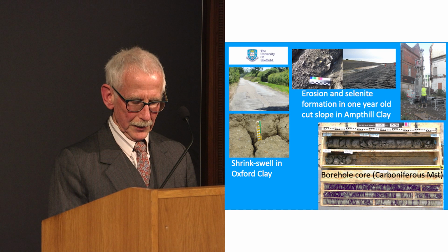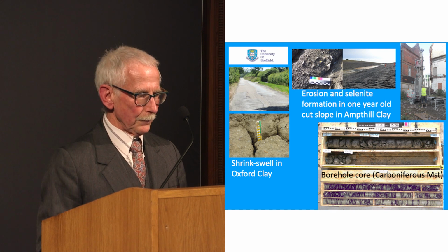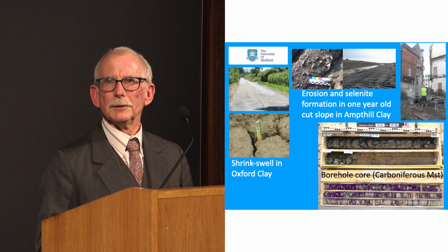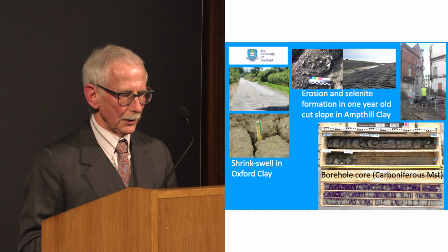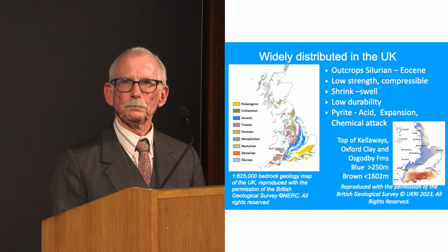And stress relief effects in the lower core on the removal of the rock from the ground has caused it to fragment in this way into small discs. And of course, if you're trying to measure the strength of the material, it's not possible.